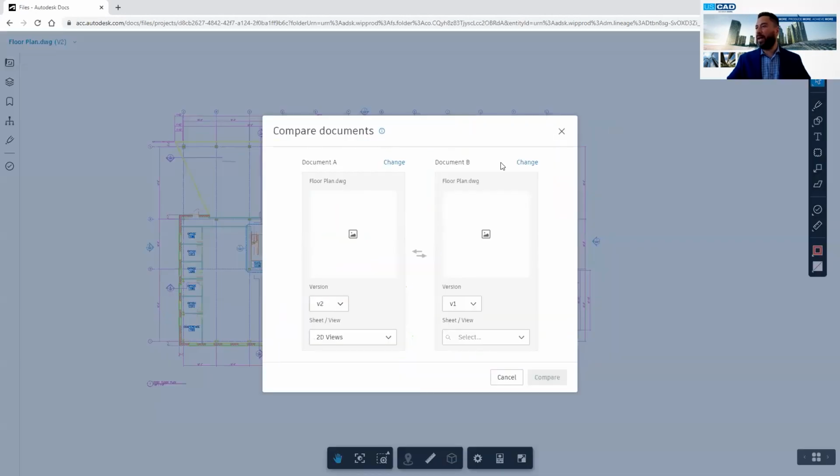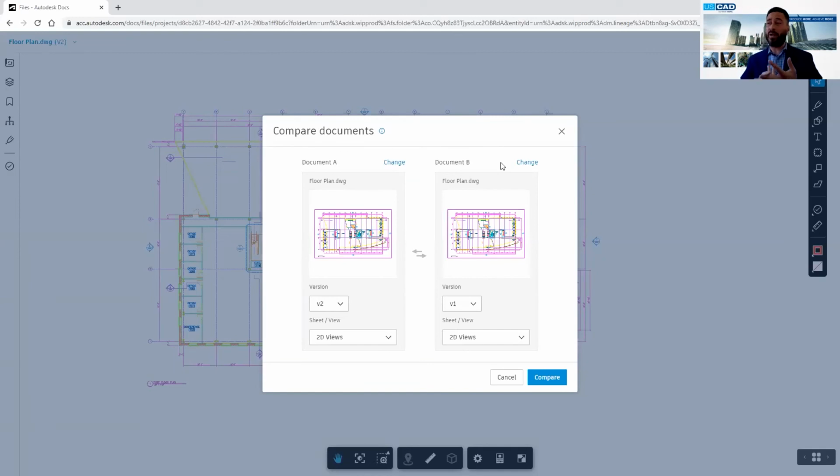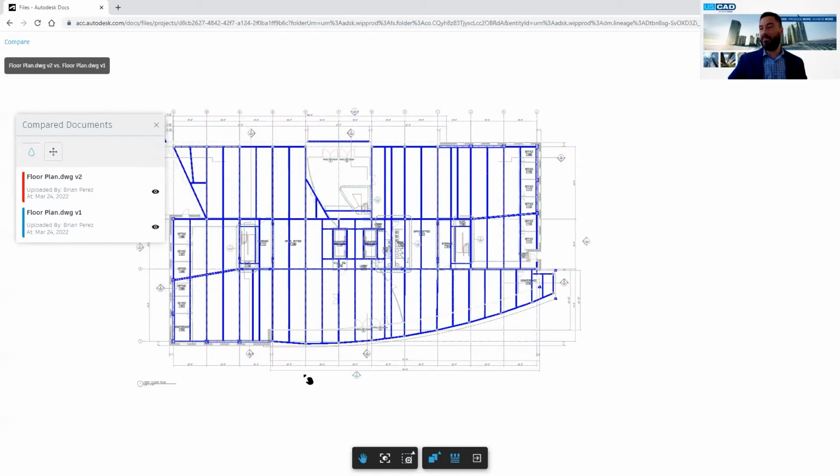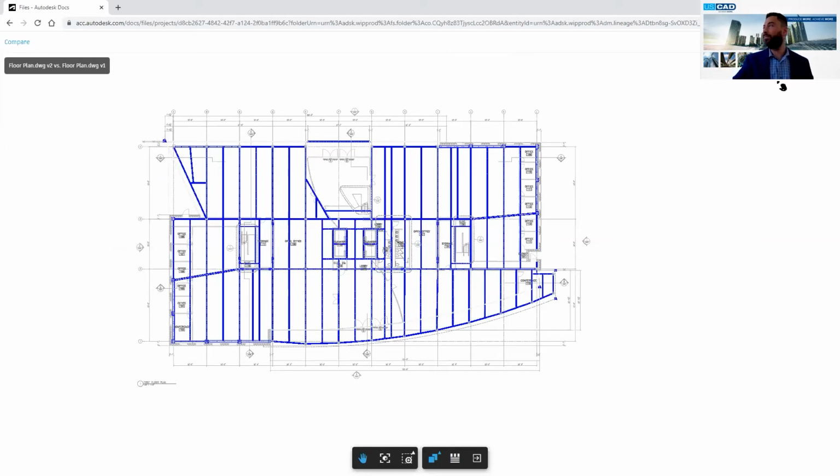And it's worth noting that for some of your documentation, as far as PDF, DWGs, and Revit files, you actually have the ability to compare the files as well. So you can actually highlight and see what has changed between the documents without ever having to open them and refer to some kind of a change log through an email.